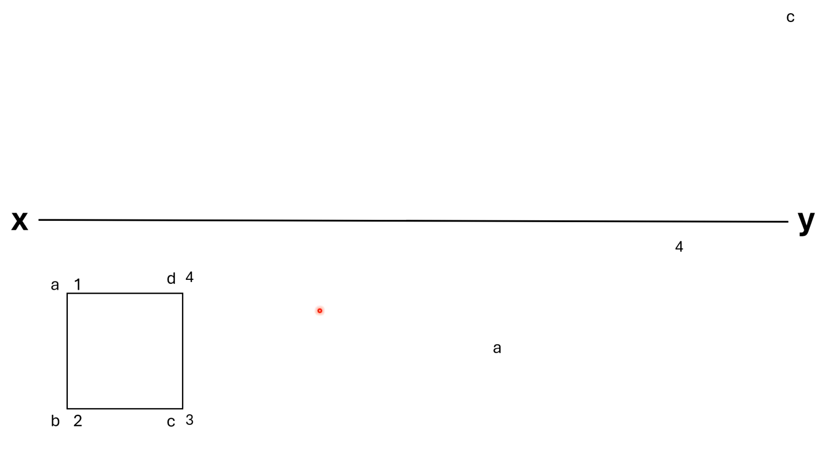As it is resting onto the horizontal plane, so I will be marking A, B, C, D on xy line because it is resting on horizontal plane. I am assuming that A, B, C, D are the bottom base and 1, 2, 3, 4 are the top base. So this will be the front view, and here it represents the height, and there will be axis also. I am avoiding axis in order to avoid the confusion in this demonstration, only for this example.